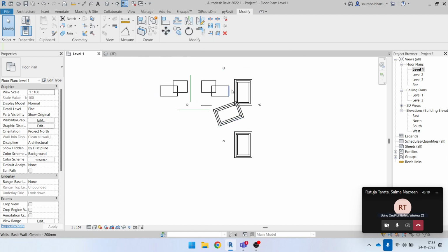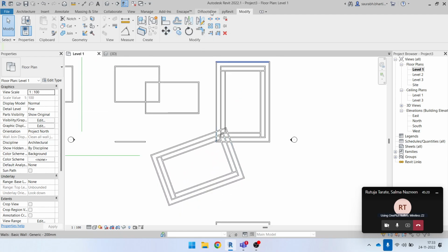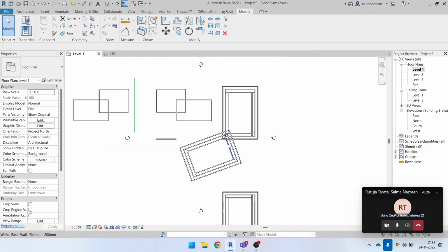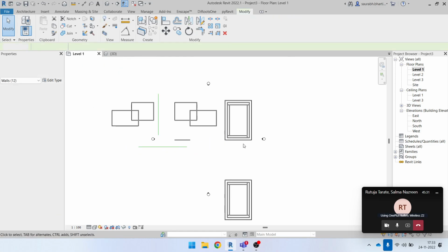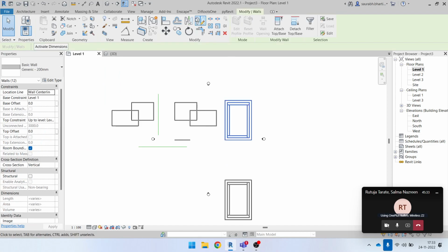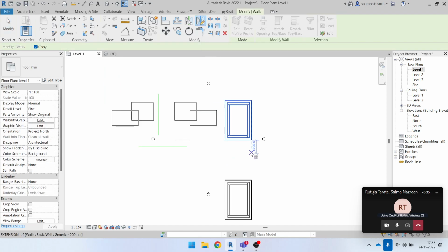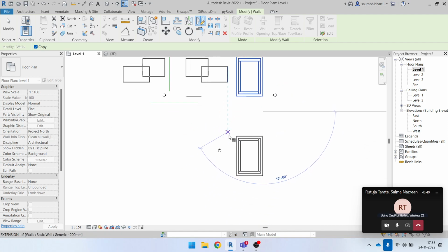So this was the draw mirror option. After that, we have this split angle option. Yes, you can also type the angle. So you select this and then click on draw mirror axis. First, select the point from where you want to mirror. Now if you move your mouse, you can see it is showing the degree, but you can use your keyboard. Like I want it at 35, so I will just write 35.